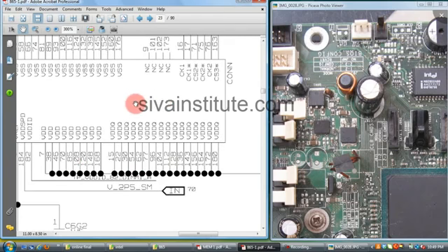You should check in the DDR1 slot supply pin numbers 7, 38, 46, 15, 22, 30, and VDD SPD, the EPROM chip supply, pin number 184. Total 184 pins.